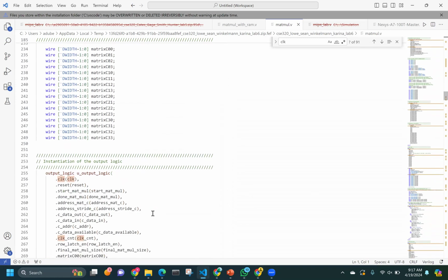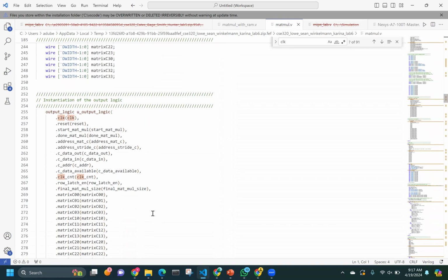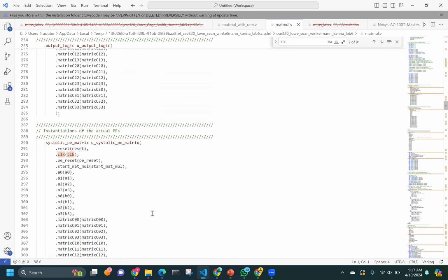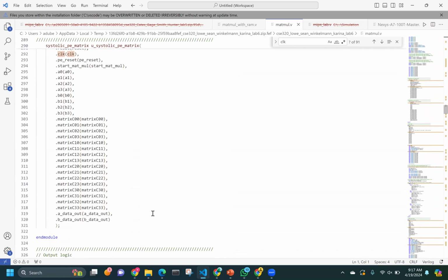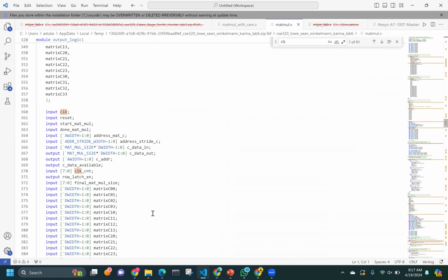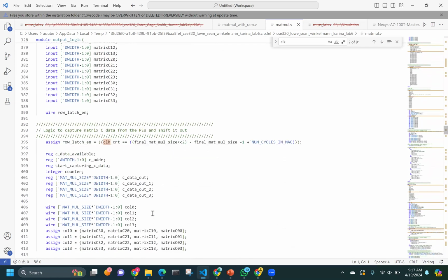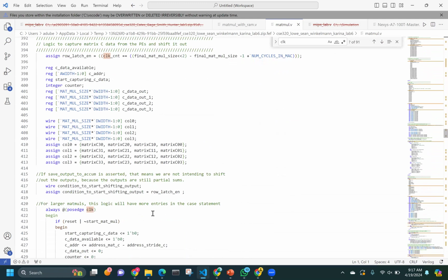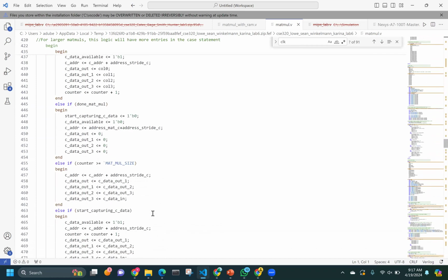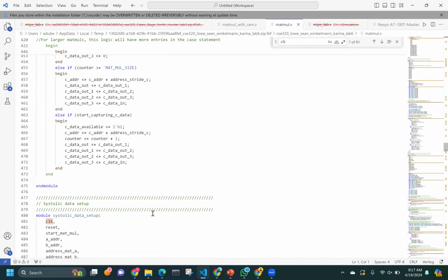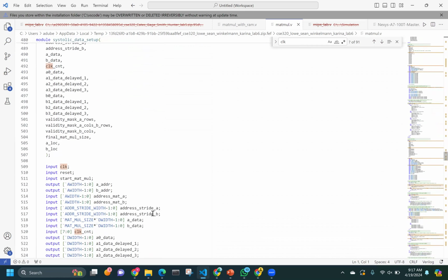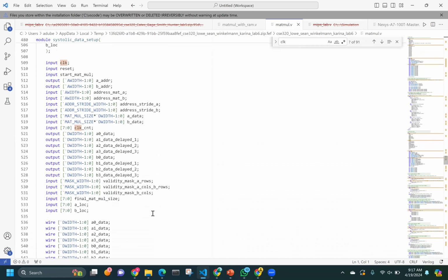All this functionality is pretty straightforward. You just have to connect wires and see what is feeding into which input, which output it feeds, and how that output is further propagated towards another input. You have certain enable signals also. Enables are used when you want to deactivate certain parts of your architecture, because in hardware everything acts simultaneously, but before the input arrives at a certain section, you can enable or disable it in order to save power.